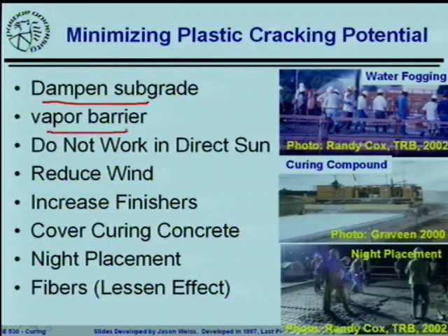Use a vapor barrier. Protect the concrete from losing water. Don't work in the direct sunlight. Right here, if you're working in the direct sunlight, higher potential for the concrete to heat up, higher evaporation. Reduce wind. Now, obviously, few of us have the powers of Evan Almighty to go out and hold up our hands and stop wind. But one of the things that you can do is you can put up windbreaks. So you can erect small walls to sort of keep the wind from hitting the surface of the concrete directly. You can basically work in a direction where you've minimized the effects of winds.